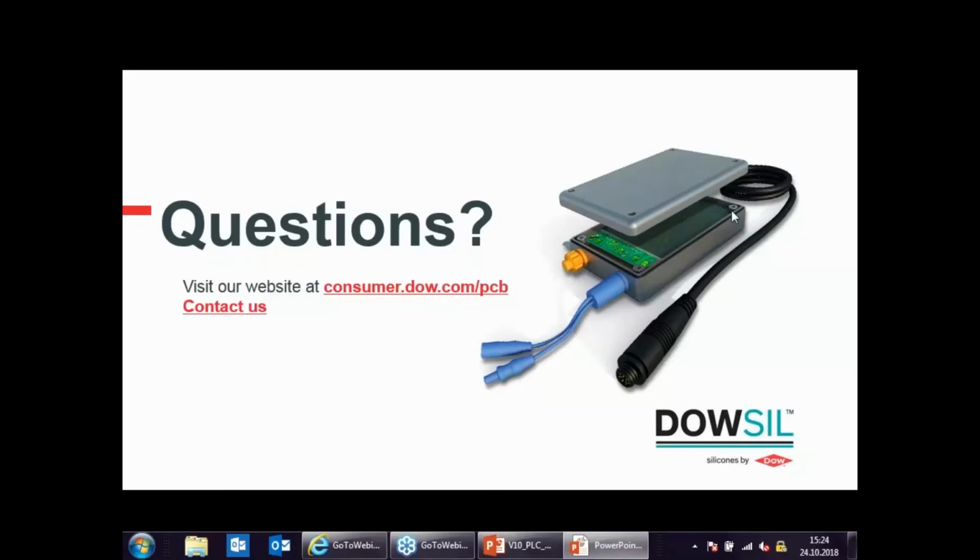But I think what this question is going for is if you can immerse the PCB in water, and oftentimes the greater issue is the insulation strength, because conformal coatings are quite thin, so you may not have the right insulation strength provided by this thin layer in order to avoid short circuits, for example.